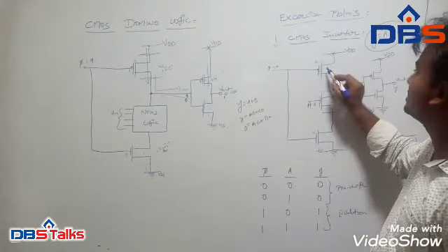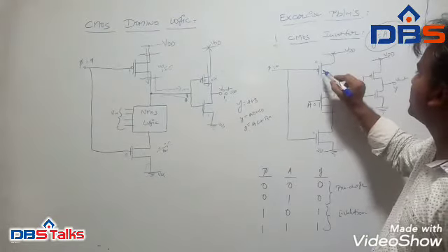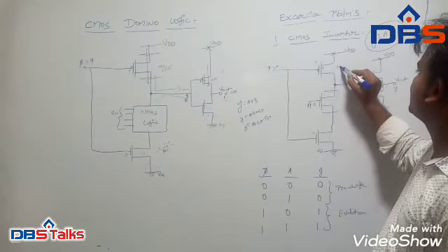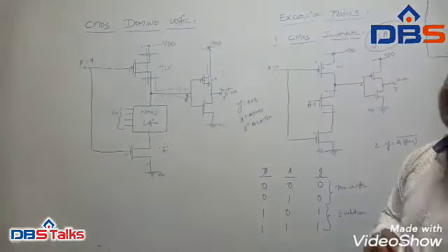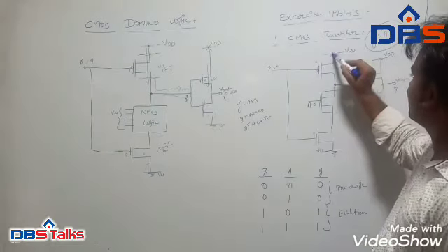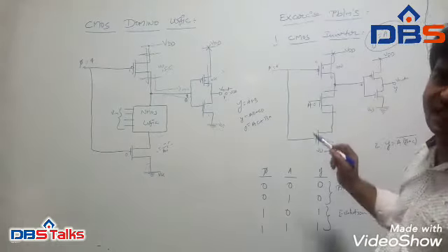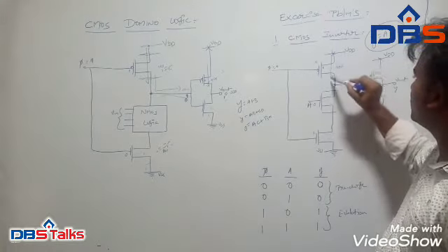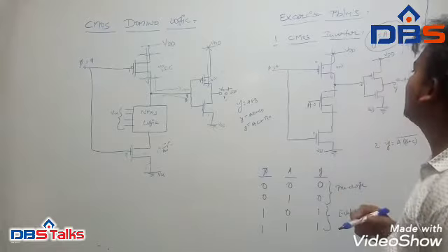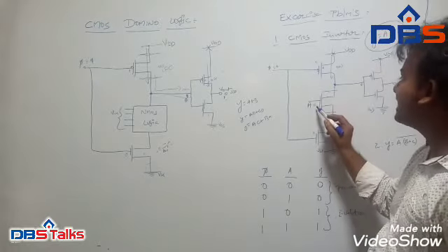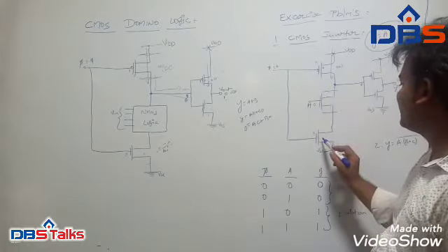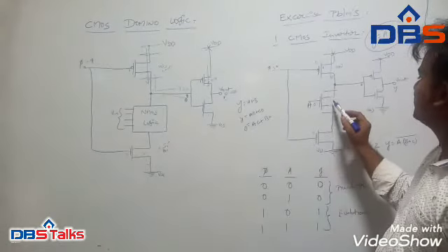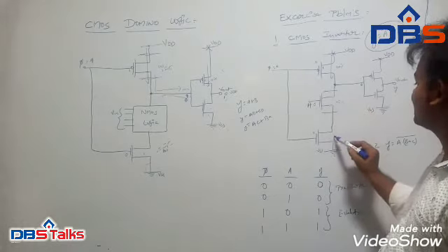For the PMOS transistor, 0 is inverted to 1, so the P-type transistor is on and acts like a closed switch, and the VDD voltage flows through this pre-charge transistor. A is 0, and the evaluation transistor input is also 0, so both transistors are off.